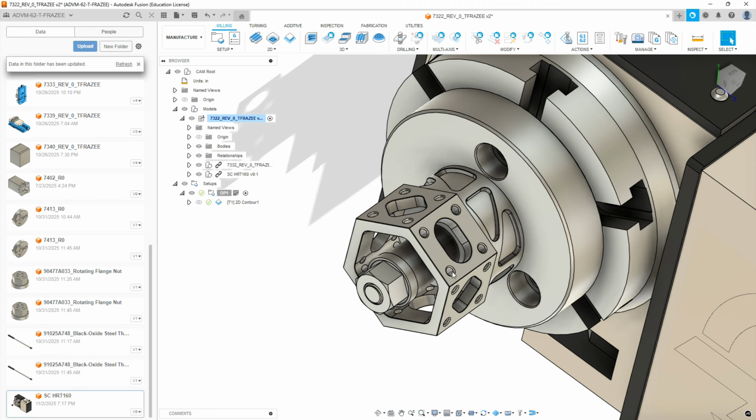This flat occurred in 6 places. This hole pattern of 4 holes also occurs in 3 places. The pocket here in that geometry only occurs in half the instances, so it occurs in 1, 2, 3 faces. And then the diamond shaped profile is going to be in 3 places. So those have to go into different indexing operations.